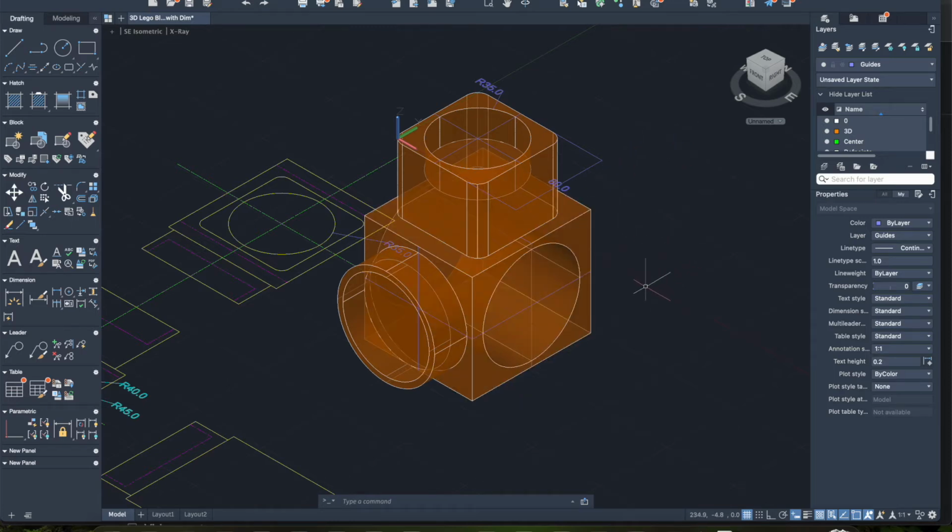Okay, so I'm also going to dimension the bottom area here. And once again, because this is way up in this area, we need to drop it down. So you type in UCS and it pulls it over. This time I'm going to select this point, bring the X over here, and bring the Y over to that point. You always find those boxes and then you know you're in the right spot, because sometimes it's hard to see the other end. And then we get our dimension tool here. Click, click, and pull. So that works.